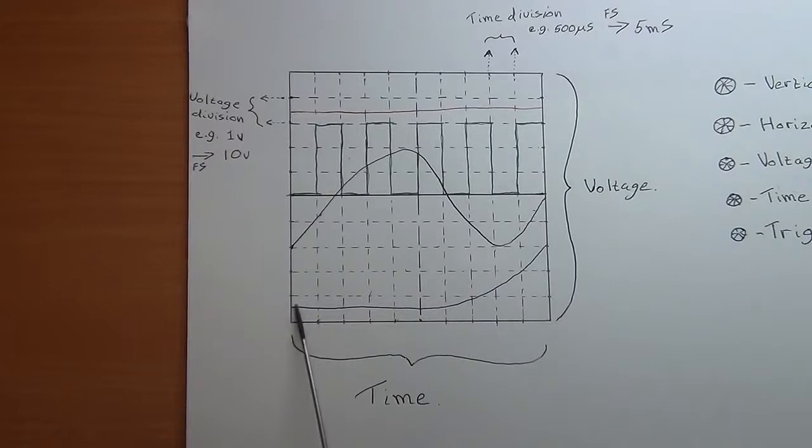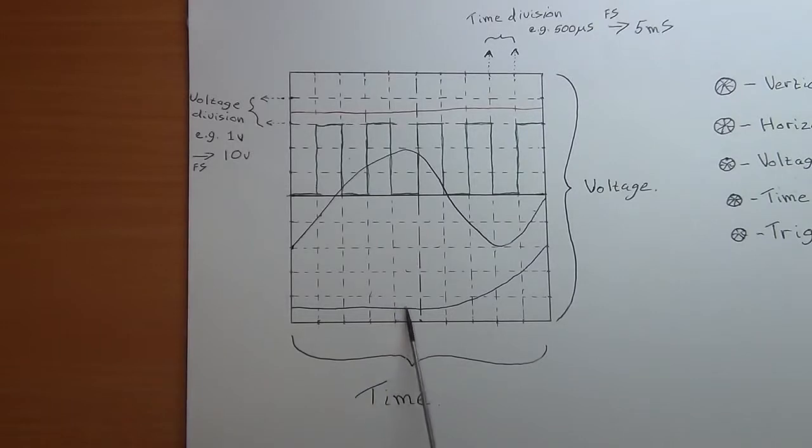Then over here, let's say we hooked this up to a capacitor that was charging over time. As you connected the capacitor and you had a battery or a variable power supply attached, if you set your time base slow enough, or even if things were happening fast, you might see a signal like this, where the charge voltage is initially low in your capacitor, and then it starts building up over time. And that would perhaps be the trace or the signal representation you would actually get on the screen in that case.